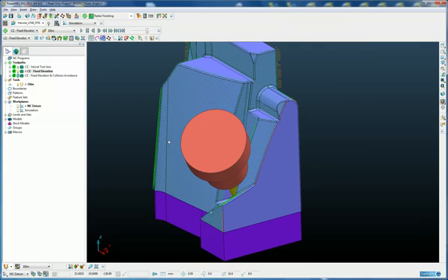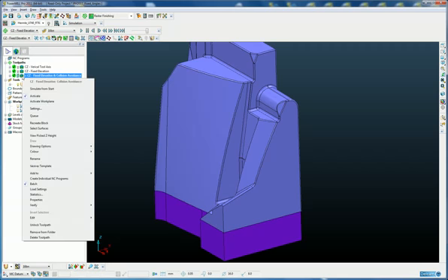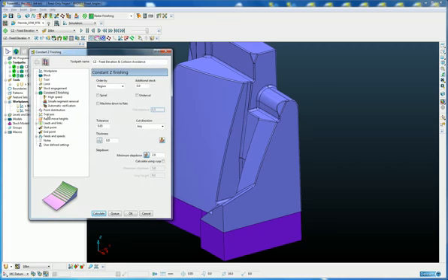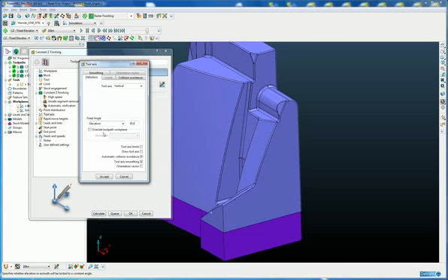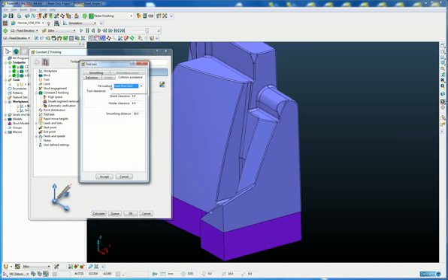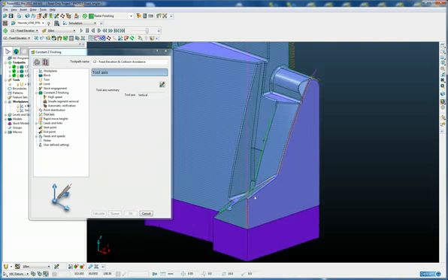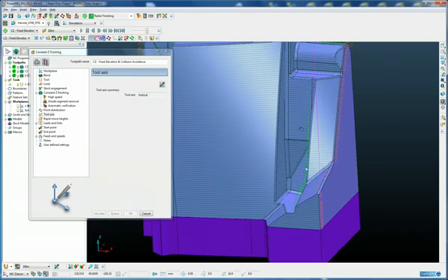the flexibility to allow us to move away from that locked angle if there are any collisions, so we can avoid the collisions without having to retract off the part. So to do this, we can use the collision avoidance in conjunction with the fixed angle definition. So on the last toolpath, on the tool axis form, we've also switched on collision avoidance with a lean and lead method, and now if we calculate, here we can see now we have a complete toolpath without any breaks